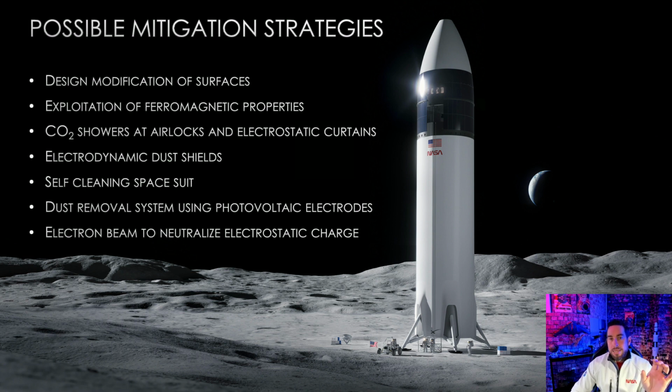One design feature of the Starship lunar lander is that when they're coming in to land, they're not going to fire up these bottom thrusters down here to land it. They're going to actually have control thrusters that are ignited from towards the top of the Starship that will help it land. So that's going to decrease the amount of force that actually impacts the lunar surface, which will decrease the amount of dust that gets kicked up during landing. So it's a pretty innovative solution.